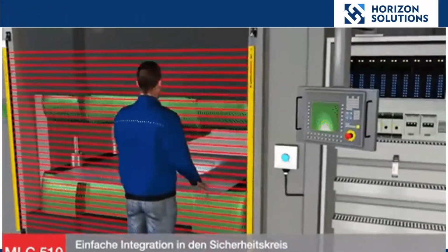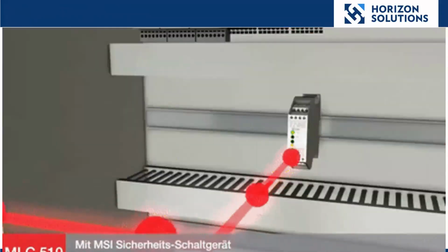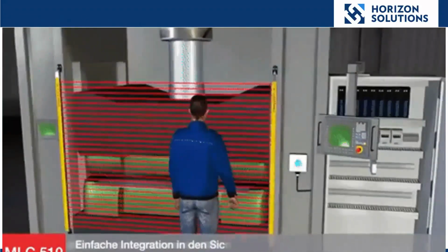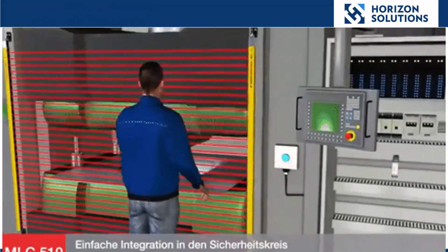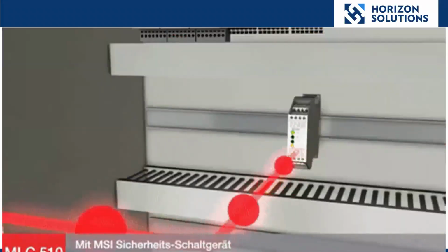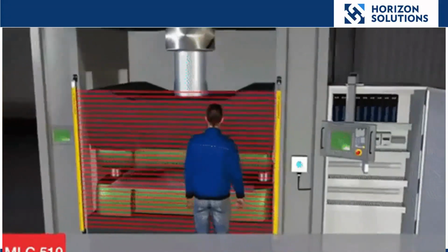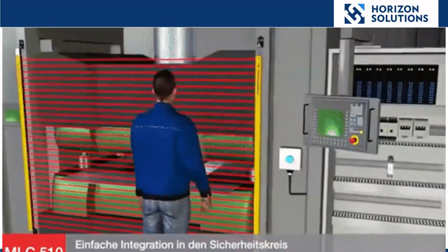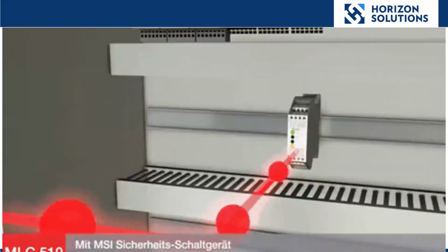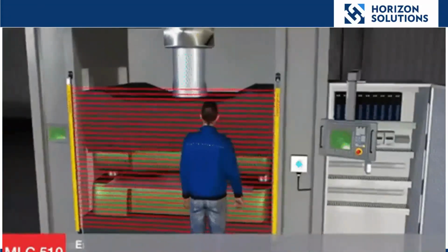So the purpose of a safety device is to stop a hazard by bringing it to a safe state prior to the operator actually reaching that hazard. As you can see here, we have this system set up with a set of light curtains providing information back to a safety relay, which is then tripping the contactor and stopping the press. Now this operation looks safe, and it looks as if it is at a low enough speed.